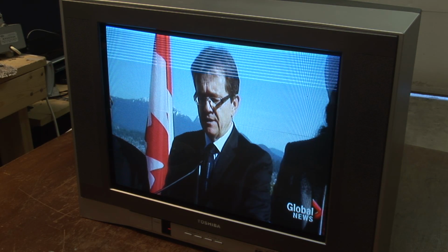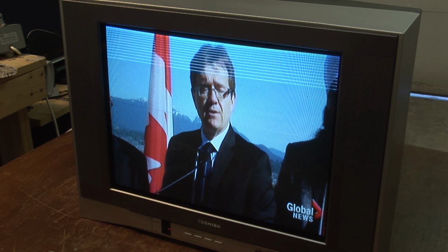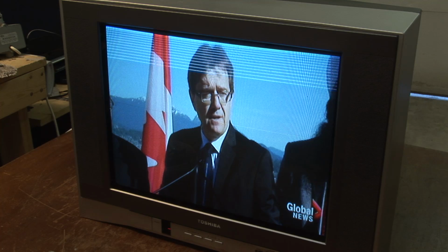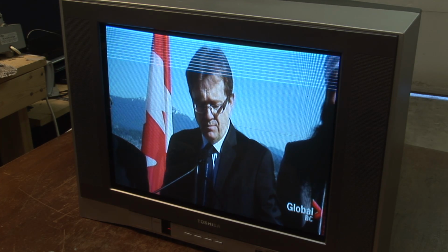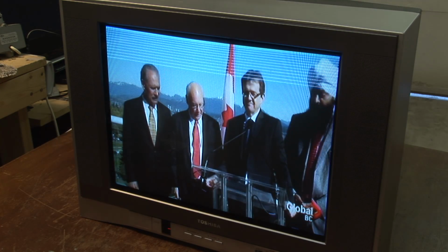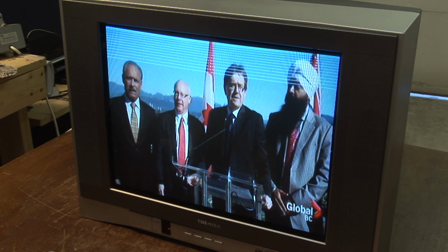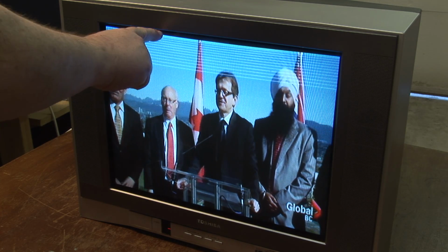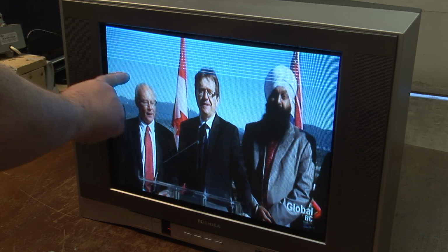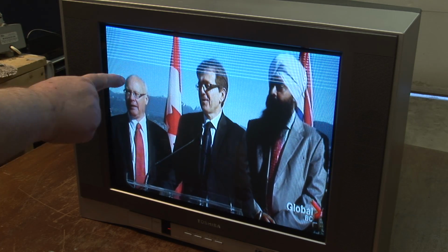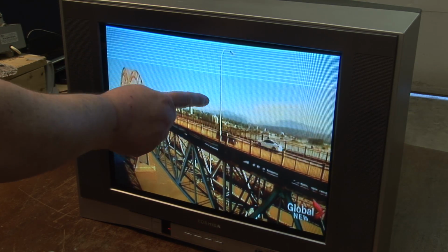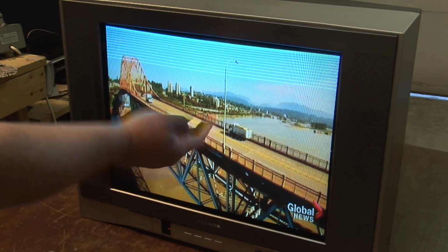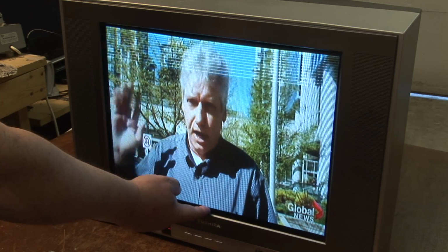But where it does make a difference is if you're shooting a CRT screen, a rolling shutter from a CMOS camera will give you, well, you've seen the picture. You get half the picture, or just half the picture blanks out. And the reason why is, in a CMOS camera, the shutter is only open line by line. As it's scanning, it'll scan all the lines one at a time, but each picture line is only active at that instant. So a phosphorus screen such as a CRT is refreshed by the scanning beam.